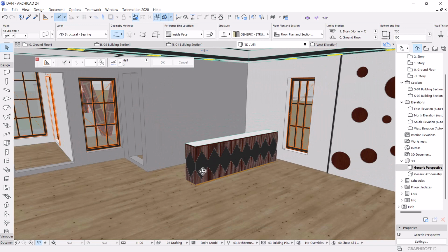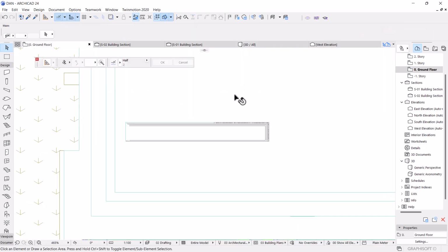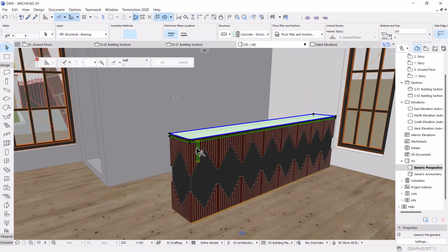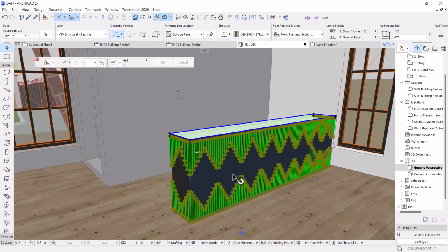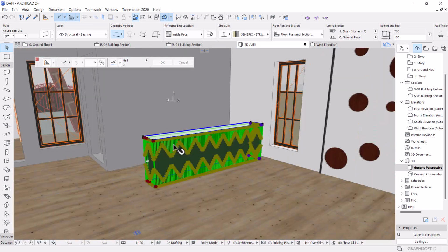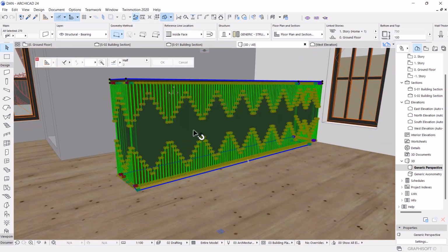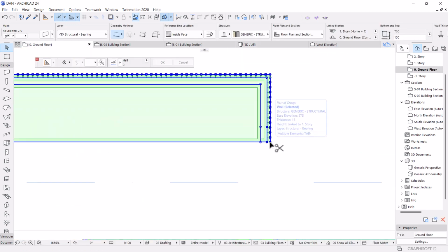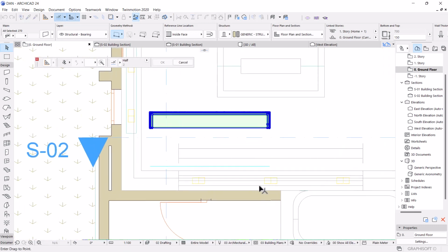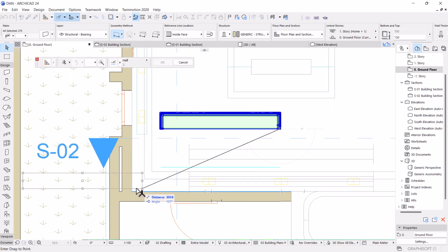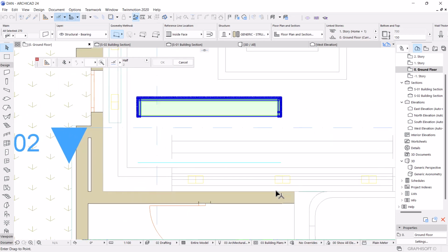And we can move it to the wall now. Before I move it to the wall, I have to select the whole thing. So the top, these guys, and suspension of groups, this. So I have to group everything together, and this one as well, Control G. Now I can move it, Control D, somewhere along the wall, but you have to make sure the space between here and here is the same. I mean, try to make sure that it is at the center. For me, I think somewhere there.